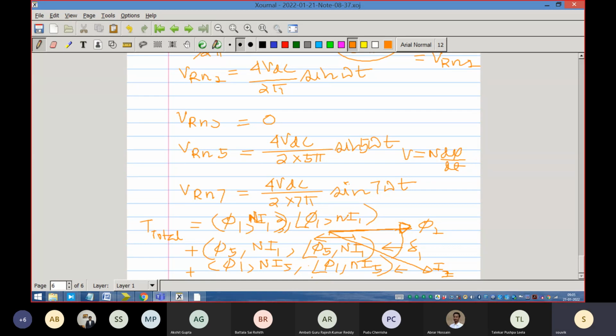If the flux is there, voltage is 90 degrees apart. This is the voltage, that is what we know, right? Because the differentiation and integration relationship holds there. So this is the voltage, and this is the flux lagging by 90 degrees, and the relationship between flux and the current is producing torque. Okay, so it would be seen here that there is a stable torque and there is some pulsating torque. That is the problem of giving harmonics to the machine.